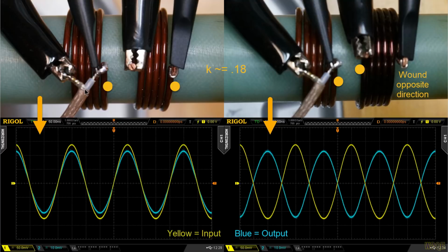I have a generator that comes in and drives this. I have an oscilloscope that's looking at the voltage. This is the ground probe of the oscilloscope, and the hot end of channel 1. Channel 2 sits here and here, and I see the two phases, the two voltages in phase. And the reason I see them in phase is because the leakage inductance is not enough to cause any phase shift with respect to the high impedance that the scope probes produce.